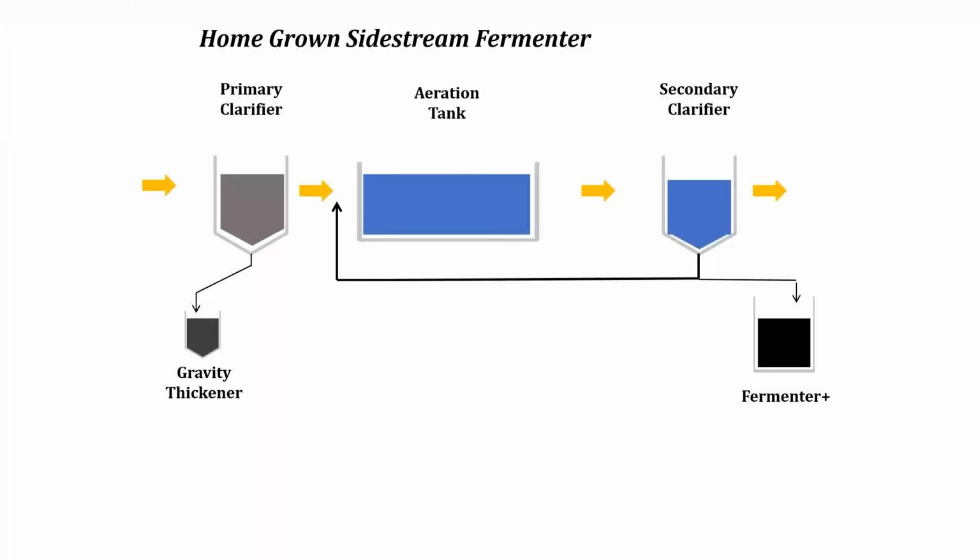And during the air off, if your air is off for more than a couple hours and it's not being mixed, you can be pretty sure that down in the bottom of that aerobic digester with the air off, it ain't aerobic no more. It's septic enough that you could actually be creating volatile fatty acids.